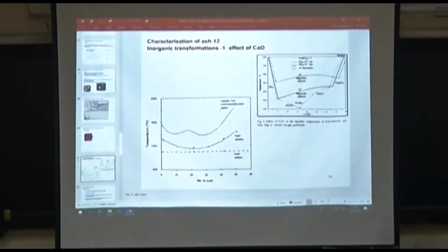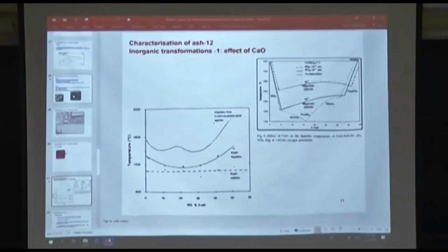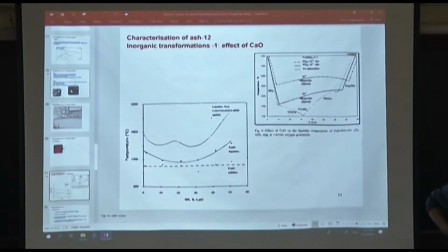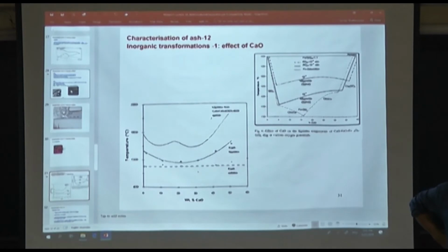So yesterday I also told that calcium, sodium, magnesium, and iron actually create problems. Silicon and aluminum, or their oxides, on their own are not problematic. But as soon as the compounds of the other four elements are present in the matrix, you start having lower temperature compounds and all sorts of other problems. So calcium is actually very unique from that perspective.